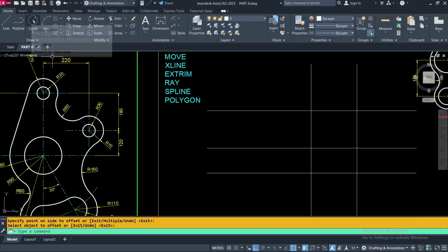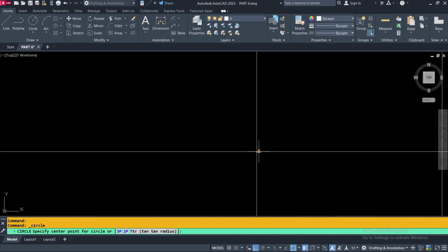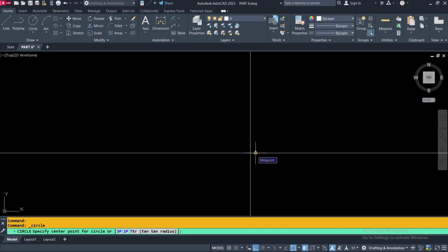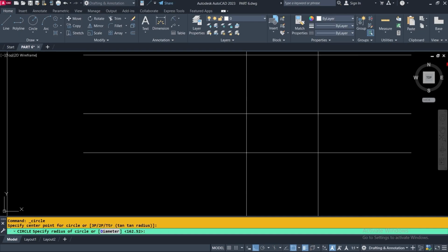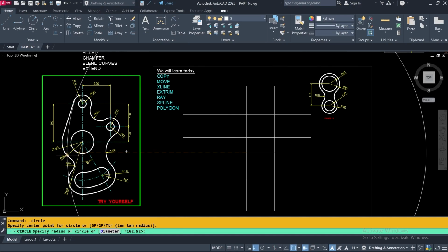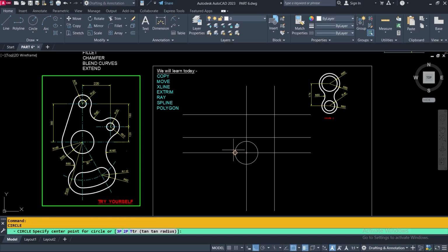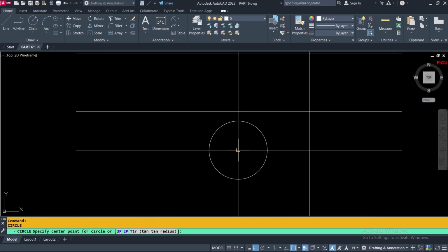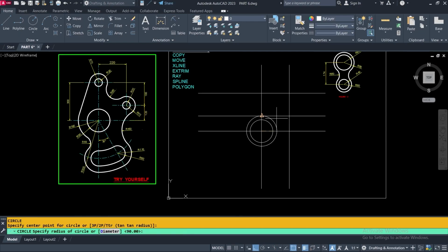Going to the circle tool, clicking here, it is showing center radius, we need that, click. Then coming here, you see here for O snap midpoint is showing, it may create problems, so I am zooming here, then taking the point, click and typing the radius value, 90 and then 160. So typing 90, again pressing enter to take the circle tool, taking this point and typing value 160, and enter. So we have got 2 circles here.